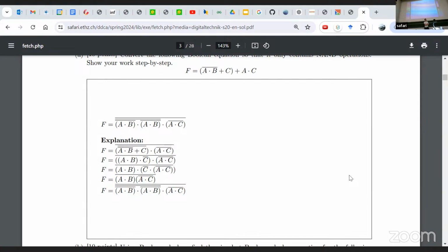Yeah, sure, but what happens, for example, if I do load word into one register, and then in the next cycle I want to use that register? It is already there, right? You wrote it already. But it only came exactly at the time when we fetched a new instruction. We don't have a race condition there. It's a good question, actually.